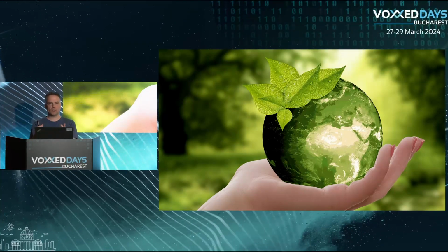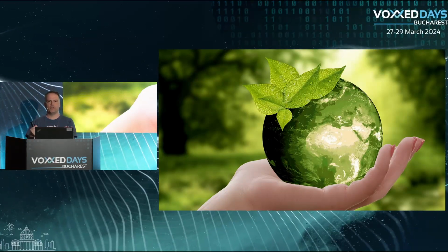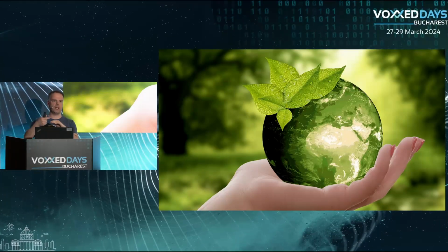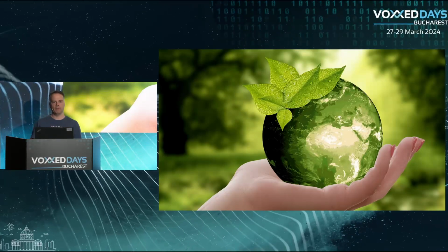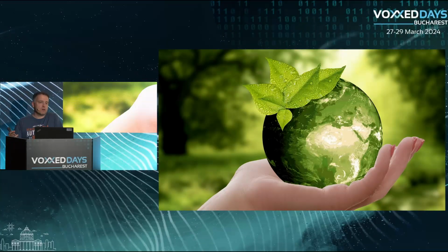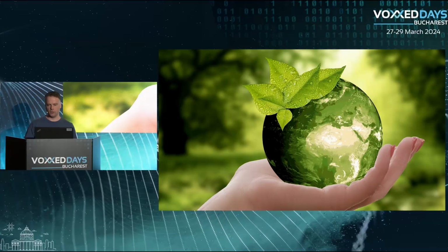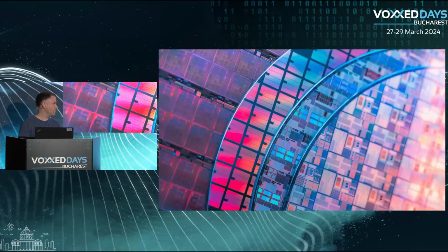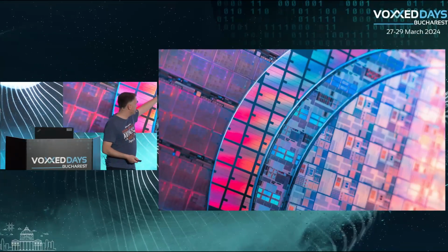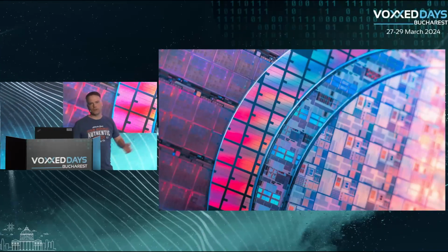For example, the transistors you want to have as small as possible. But we also have connecting layers, and there it doesn't matter if it's printed a bit bigger. So we can use the new machines for some layers, and the old machines for other layers, and combine them. One of the advantages of the older machines is that they're often cheaper, and they can process more wafers an hour. So companies mix the usage. And then you get wafers like this. These are real chips that are printed. And here you can see it's going to the edges. These ones are basically worthless at the edges because it's only half a chip.